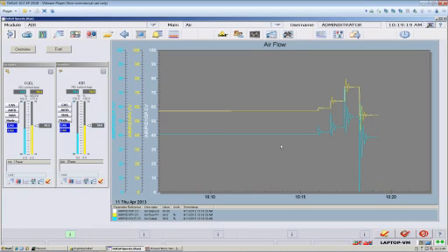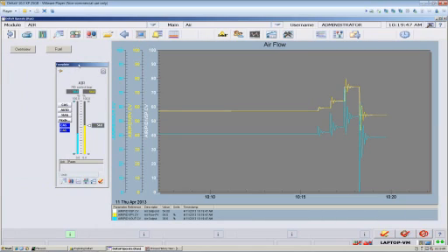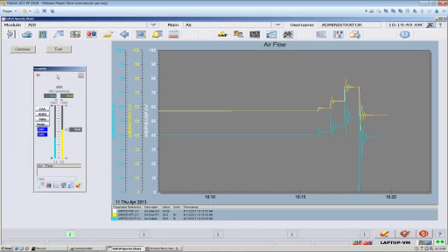In this trace, controller output, where I'm telling my valve to go, is this blue trace here, blue, cyan, whatever you want to call that. The white line is set point, the flow I want. And the yellow is my actual PV or measurement, the flow I'm really getting in response to these valve positions. So let's start. Let's close the fuel faceplate to get it out of the way, and we'll focus on air for now. Let's start by putting this in manual.